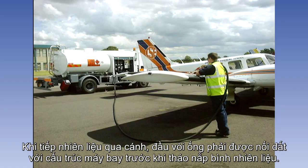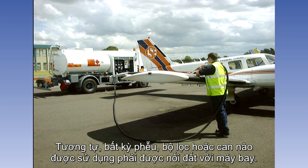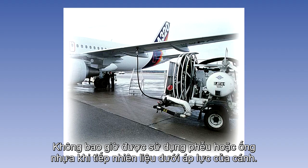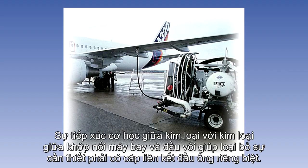When overwing refueling, the hose nozzle must be bonded to the aircraft structure before removing the tank filler cap. Similarly, any funnels, filters or cans that are used must be bonded to the aircraft. Plastic funnels or pipes must never be used. When underwing pressure refueling, the mechanical metal-to-metal contact between the aircraft fitting and the nozzle end eliminates the need for a separate hose end bonding cable.